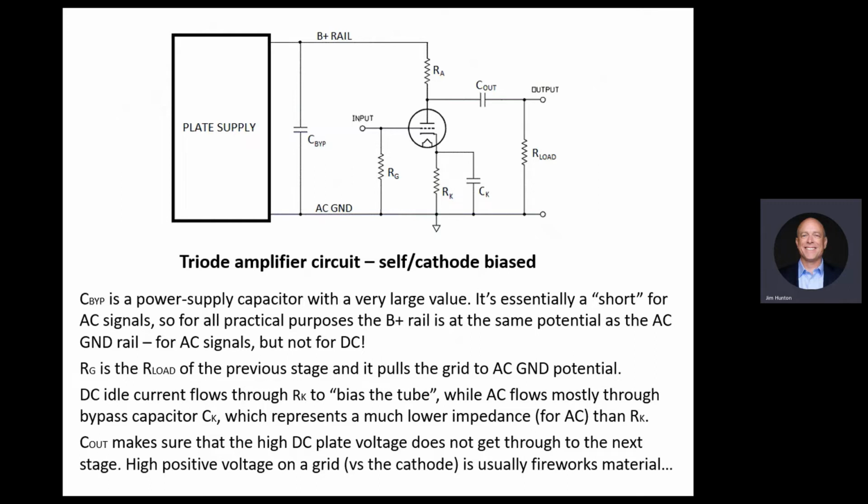And you think that this is just to retain current from the power supply. It's not. Okay? People bullshit about signal path capacitors versus supply bypass capacitors. This is a signal path capacitor. It looks like a supply capacitor because it does function to hold current or charge for the tube, so the supply doesn't sag, when the tube conducts more or less current.